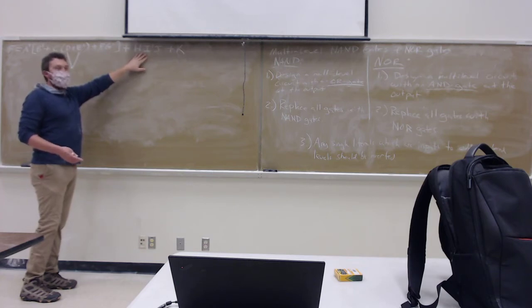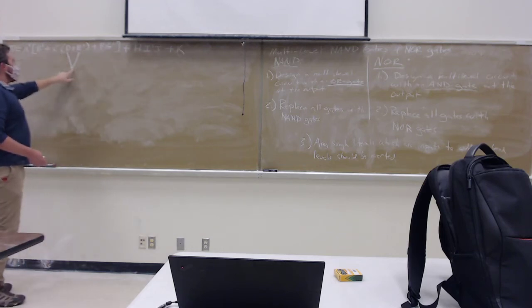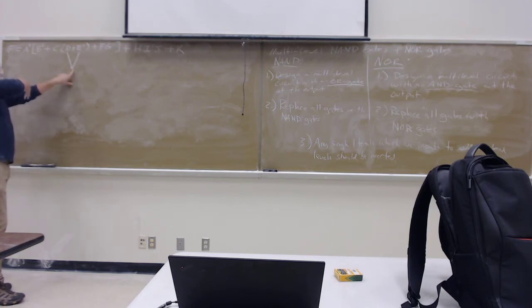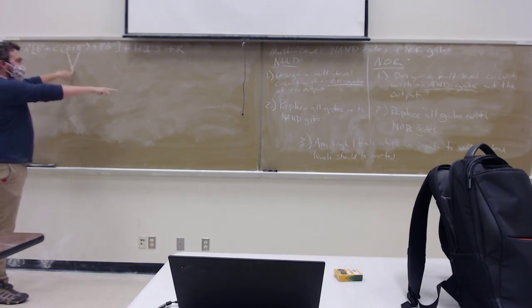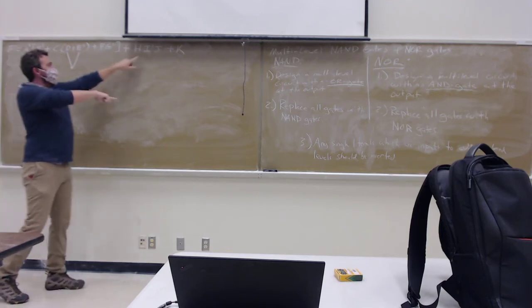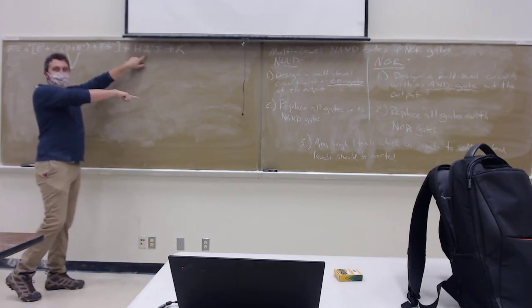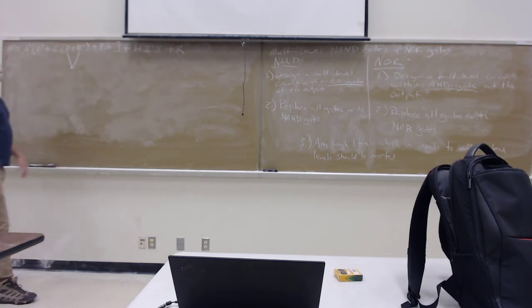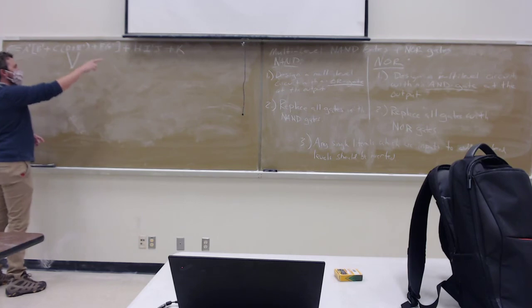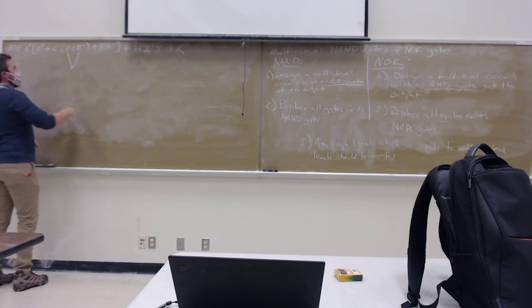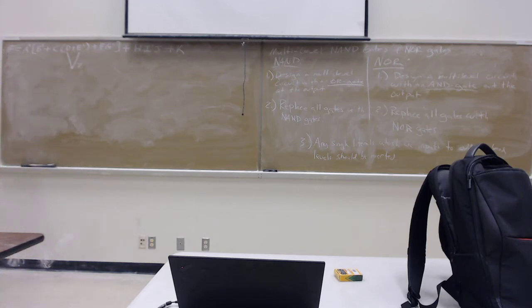And then we actually could do that, but that is going to drastically change the outcome, right? Because if we start here, with this OR operation first, in the input level, that's going to change what the output gate has to be, right? And if we start here on the AND gate, we're going to change whatever the output gate is going to be here. So while it doesn't necessarily matter on the surface, it might matter if you're asked to find a specific type of circuit. It might matter which one you start with, if you start with an AND level or start with an OR gate level. We're going to go ahead and start with an OR gate level just because. So that's level 2.